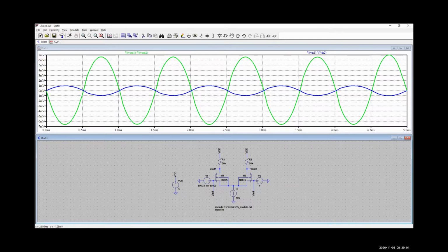So what is my gain here? About a millivolt, or maybe half a millivolt because of the... So the blue curve is my input signal and the green curve is my output signal. Oh, sorry. It's like a gain of 6 or something like that. Yeah, well, I would argue it's a little closer to 7, but yeah, somewhere between 6 and 7.